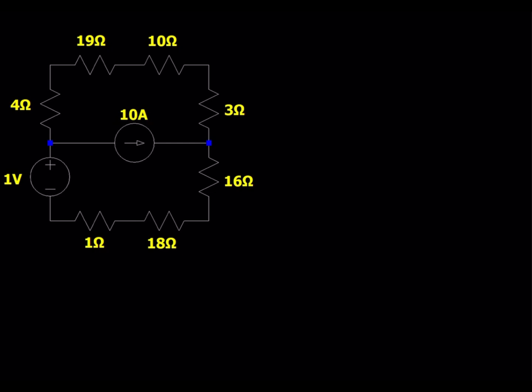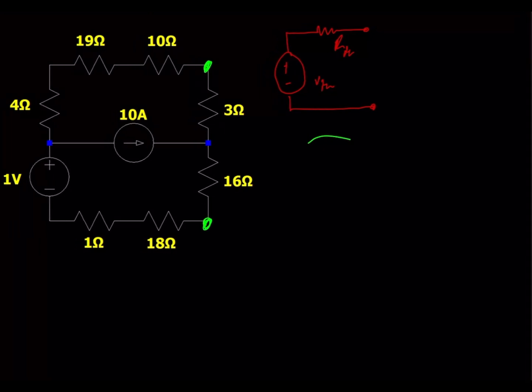So for this circuit, we'll perform Thevenin's theorem. Now, when doing this theorem, you can elect any two terminals from the circuit. So they could be these terminals, they could be these terminals, it really is arbitrary what you choose, but the end goal is to get that simplified circuit model here with some independent voltage source and then some resistance. So this will be V Thevenin and then R Thevenin. This is the end goal. So for this circuit, we'll actually perform it at these two terminals. We're trying to replicate the circuit's behavior, but simplify it so it looks like this.